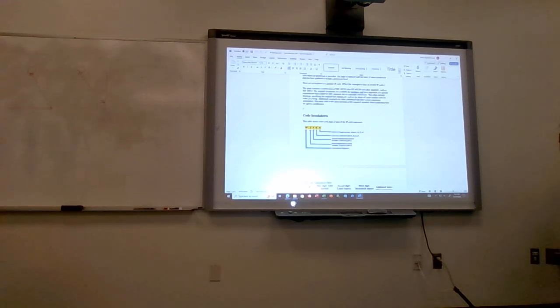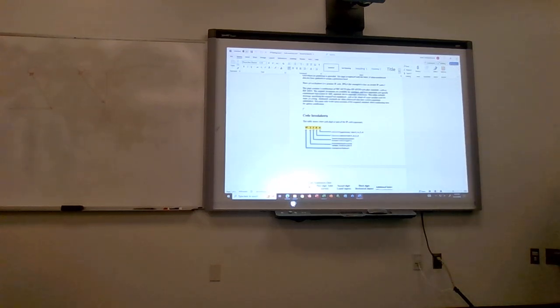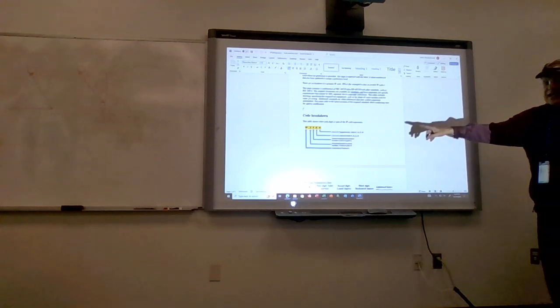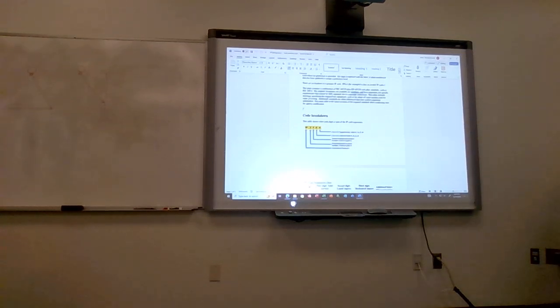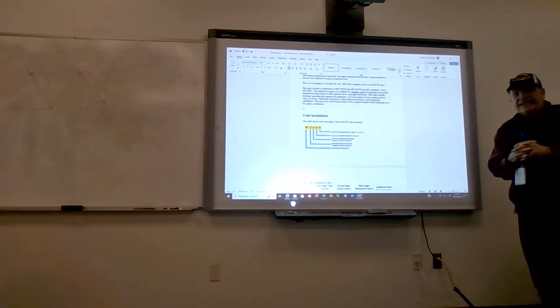So when we're talking about liquids, what we're looking for is an IP65 rating. The 6 stands for what kind of liquids can penetrate under what pressure, 1 atmosphere of pressure, 3 atmospheres of pressure, et cetera. Can everything be submerged? Well, that's the second number there. So IP65 would allow us to shoot a hose at a fixture and not penetrate. But if we wanted to put something underwater, we'd have to have an IP68 rating. Pretty simple.